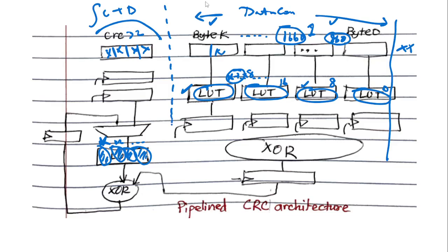So CRC works very much like a function. Now, if you find it easier, at this point I would stop and say, if you don't understand the table-based approach, if it's getting harder for you to understand, then stay with the function-based approach, because it's so much easier. You know already the functions, you divide them up into different sets, and then you do the pipelining, right? It's very, very simple. Tables are a little bit more complicated, but it is also simple to understand once you grasp it. If you have the memories available to you, the table-based approach is so much faster, because there is no timing to meet.